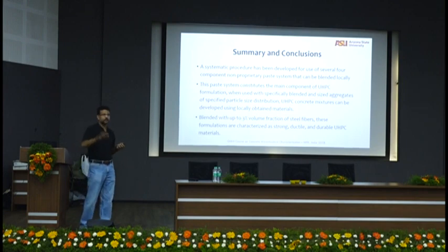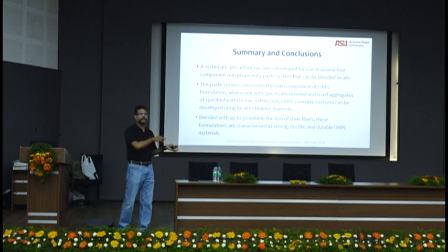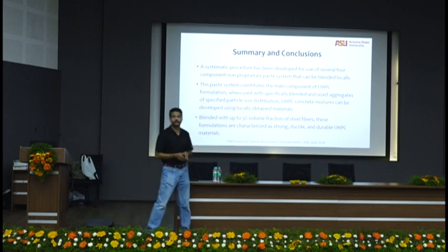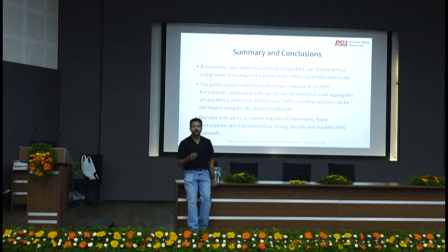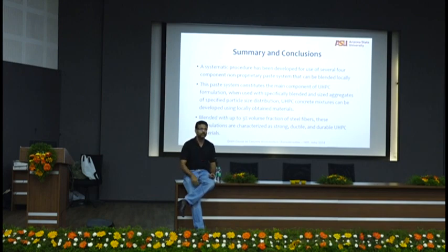So some of the ideas that we talked about in the morning: particle packing, implementation of all of that in the actual structure, and the quality control has been extremely good. Quality control in the US is typically not a problem for concretes, but in this case we had to have some additional measures for packing. We had to check the particle size distribution for all the raw materials that were coming in to make sure that they get the predicted strengths that we told them they'd get. And eventually, at 90 days, they got close to 200 megapascals.